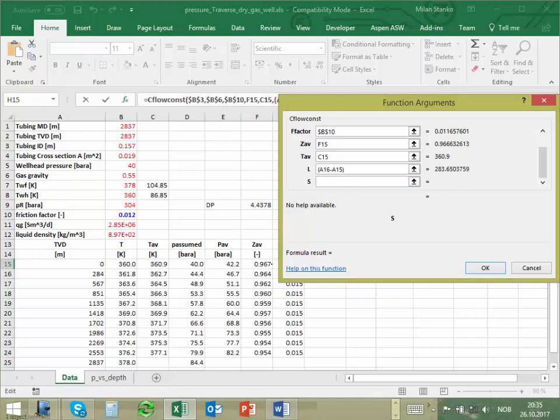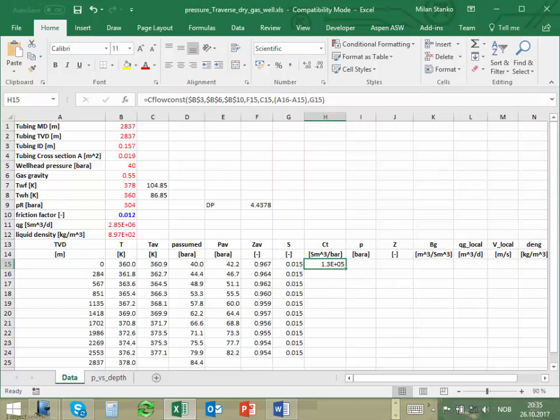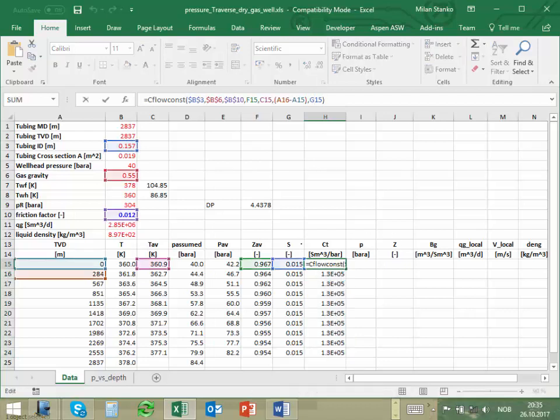And it is also using S, and we have it here. Okay, remember how much we had for the full well? 42,000, I think. And now we are getting 130,000. Does that make sense? Well, yeah, because the pipe is much shorter. So the pipe, if I put a certain pressure drop, is going to give you much more rate than a longer pipe. Yes? Okay, finally, if we didn't make any mistake, we calculate the CT for each section and the S for each section.